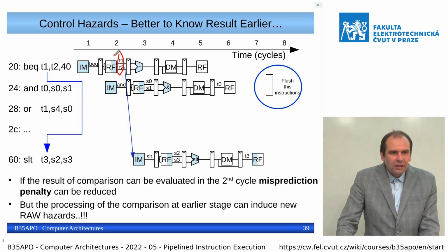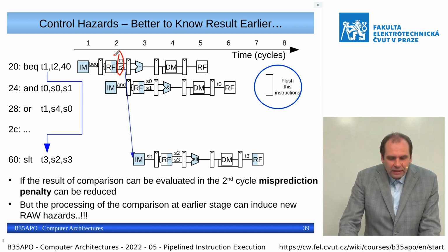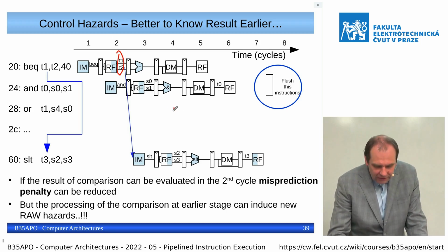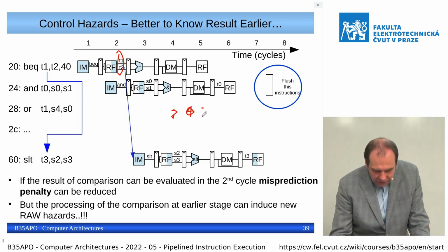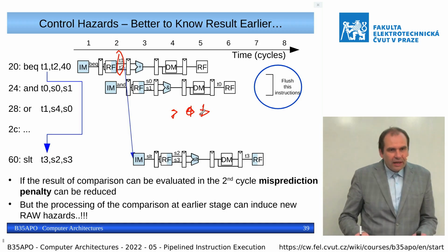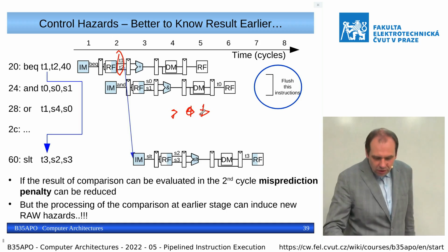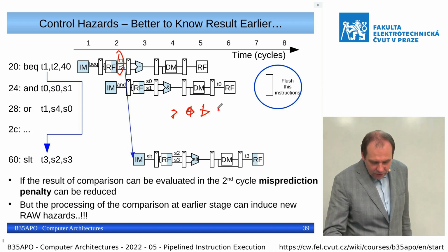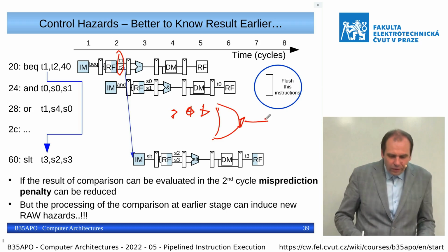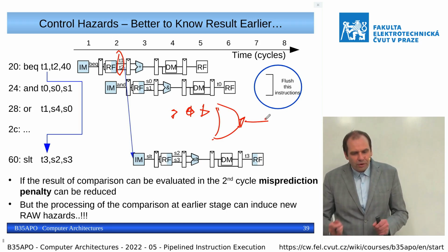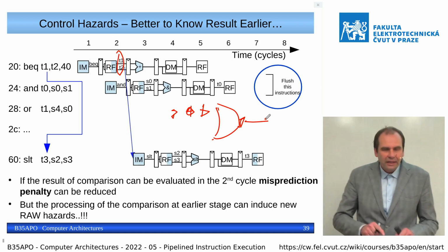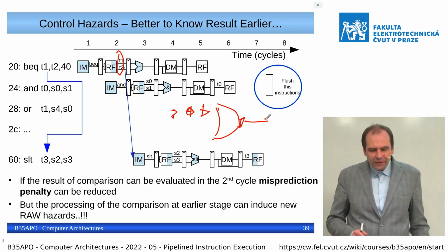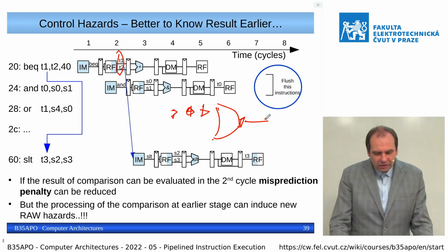You can use bitwise A XOR B for each bit, and then a NOR to connect those results together. Exclusive OR gives 1 if there is a difference between those single bit signals, and if there is any such difference, then it means that there is no equality.